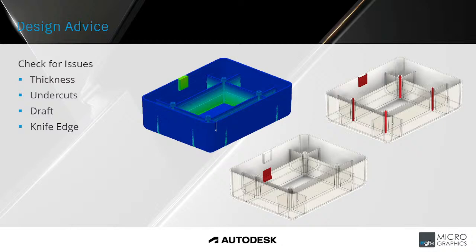So that's the top left image there that's shaded in blue and green. We can see the thickness change, and we can highlight some potential issues where we see the green stripes on the outside of the part. That's where we are potentially going outside of our required thickness. We can maybe see some sink marks there in that component. The bottom image here is showing us undercuts.